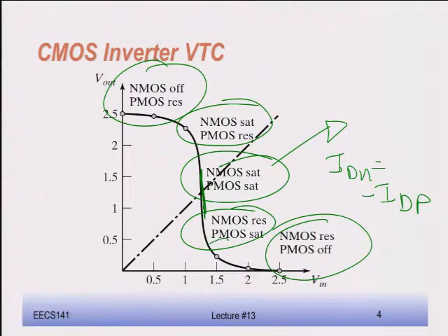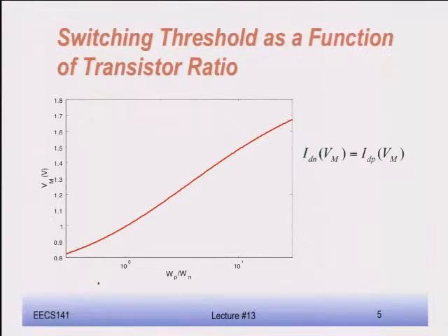Similarly, we can do the same thing in the VIH and VIL regions. There you see that we typically will have the NMOS in saturation, PMOS in linear mode for the VIL, and for the VIH it's just the opposite. Okay? So that's doing that. Then you can solve it, then you find your voltage transfer characteristic. For instance, I can actually find the point Vm.